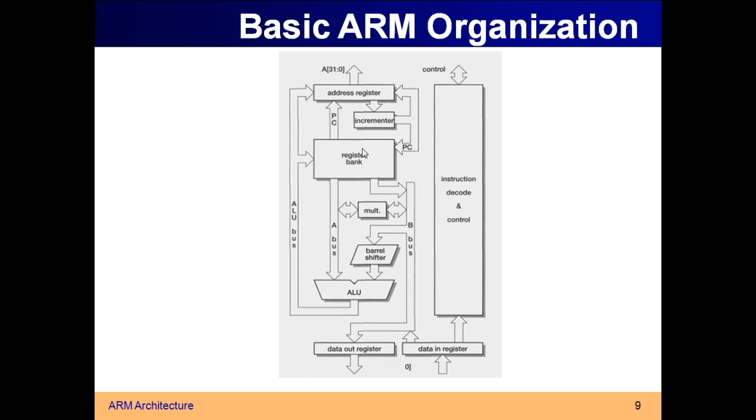So the register file is nothing but a collection of registers, in which you store the data. Let us take, if you want to add 1 and 2, 1 and 2 will be in two registers, right? The first operand will be taken to the ALU through a path known as a bus. What do you mean by bus? It is a path through which you can send the data or instruction, right?